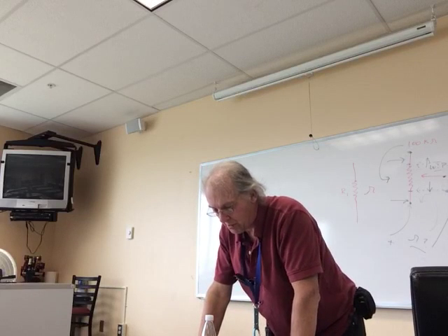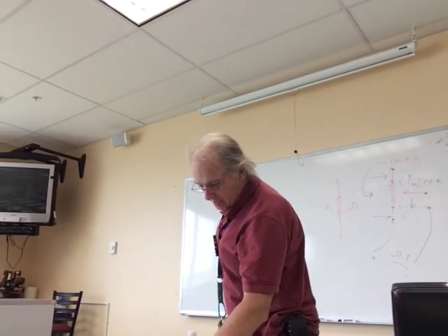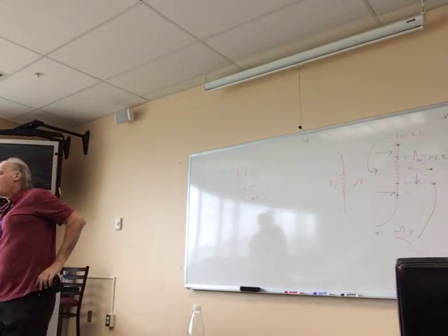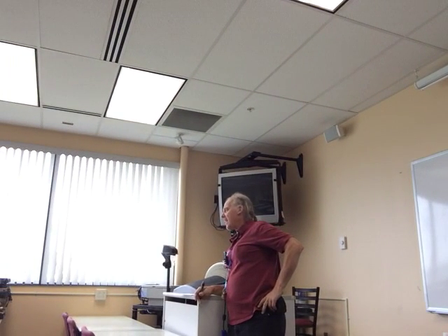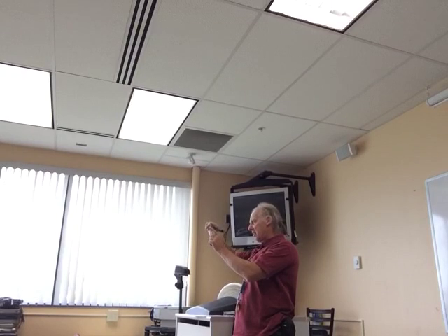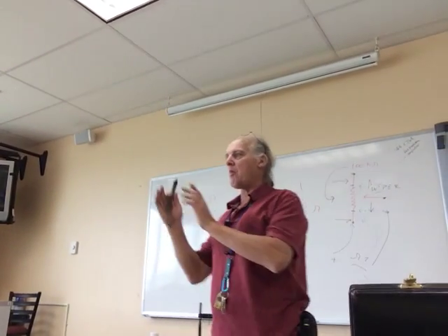When you calculate the current in the circuit, you're going to see, well, they have a 1K and a 10K. You're going to see a tenth of the current through the 10K. Okay? So it's going to split up. That 1 milliamp is going to be 1 milliamp. A tenth of it is going to go through the 10K. The rest of it's going to go through the 1K. The upper resistors, they're just voltage dividers, but nothing's happening with those. They look like a limit resistor of a single resistor in series if you look at the total. So you have to be really careful. One will affect the other.